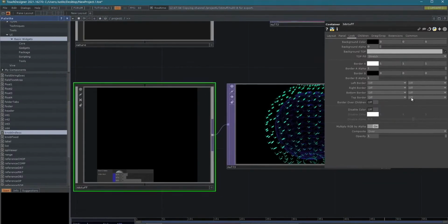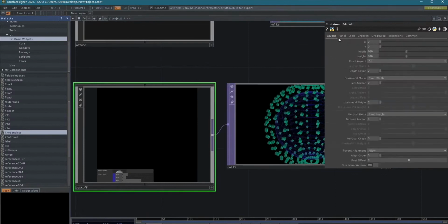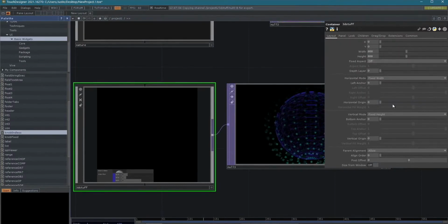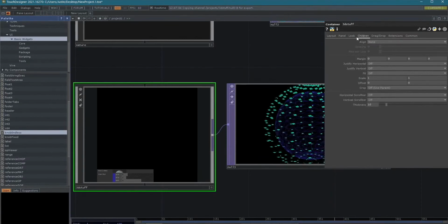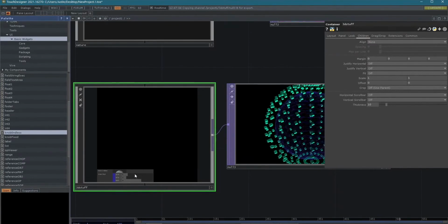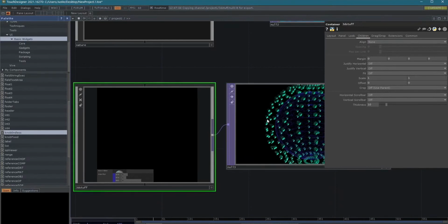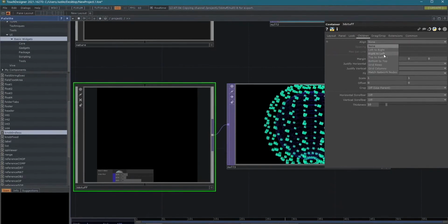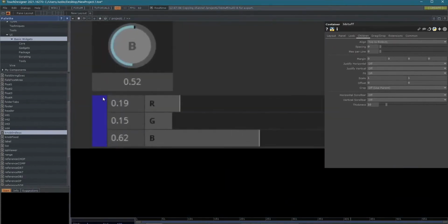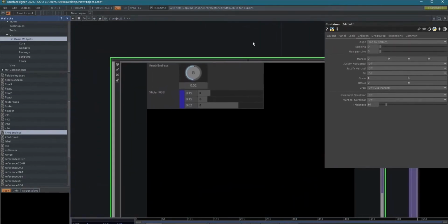We're just using this as a control panel now. So if we go back to layout, I'm sorry, it's in children. So all of those knobs and sliders and everything are children elements of that container. So I'm going to click on align and say top to bottom.